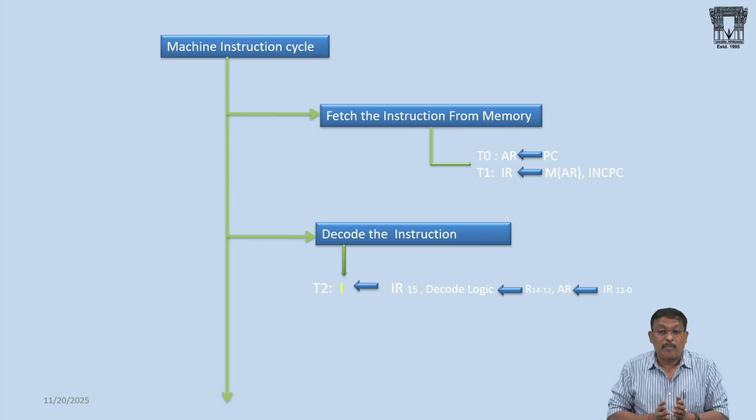So the processor may require a wait cycle to access the data from the device. You understood? That is the reason why you may pause the processor execution. You may force the processor into the idle state by introducing the no operation. Inherently, I am doing a wait. I am providing a significant delay. That is a no operation.